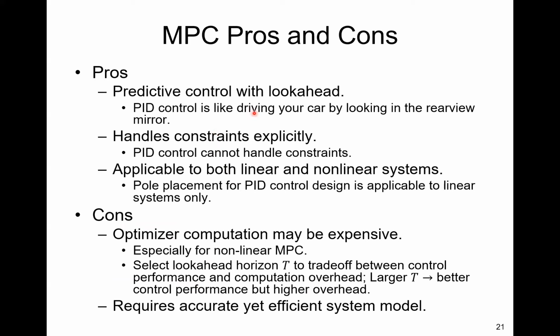So, MPC is also applicable to both linear and nonlinear systems, whereas for PID control, the pole placement method is applicable to only linear systems. The cons are that the optimizer computation may be expensive, especially for a nonlinear MPC.